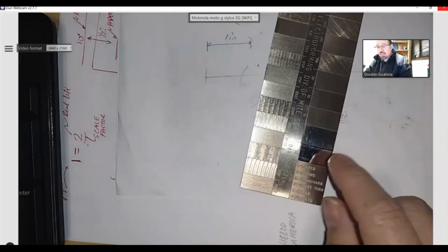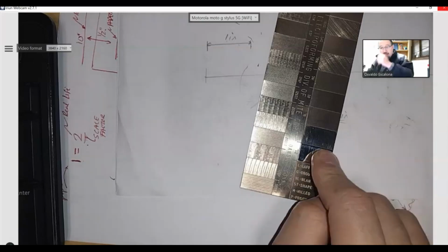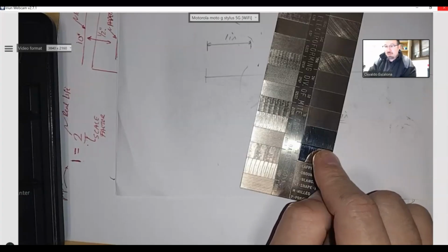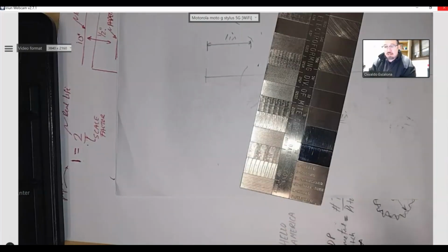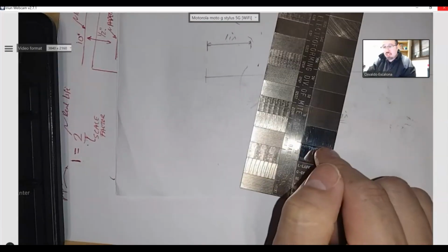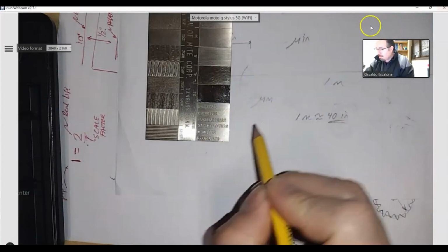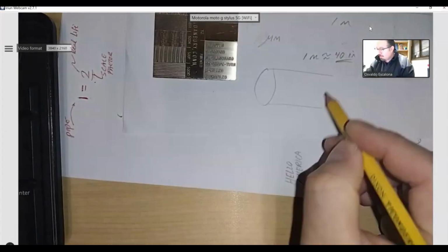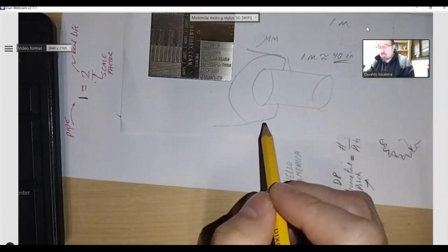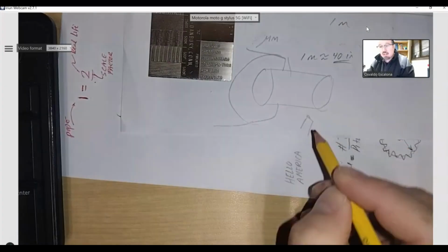Right? Before I can get it to the lapping, which is the buffing, I will have to go through the milling process, roughing, semi-roughing, finish. I mean, all of these are called either milling or the lathe, right? We call that turning if it's on the lathe. Then maybe say we started with rough turning, semi-finish turning, right? So you start with a big one like this, right? You grab it, like if you want to have a drill, you grab the material, then you come with a tool, right? And you take away material.